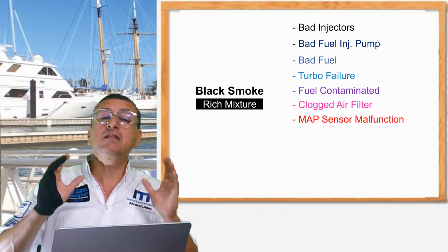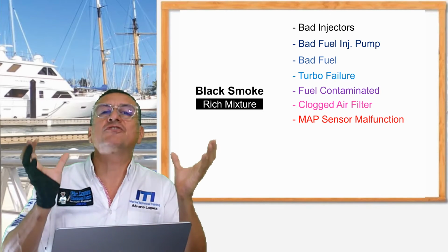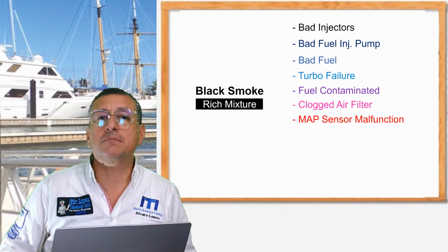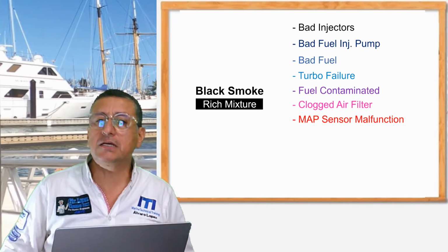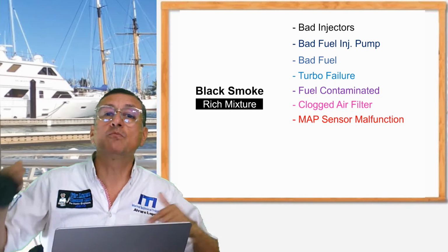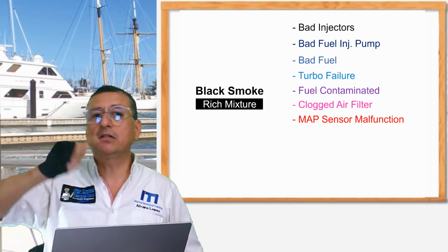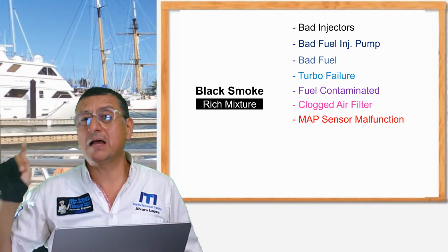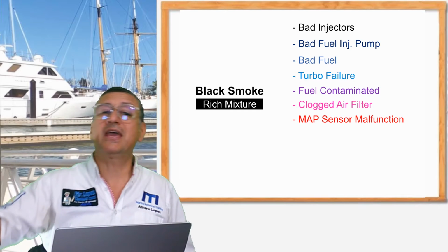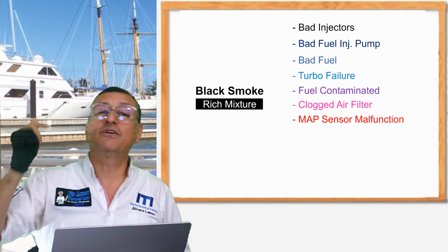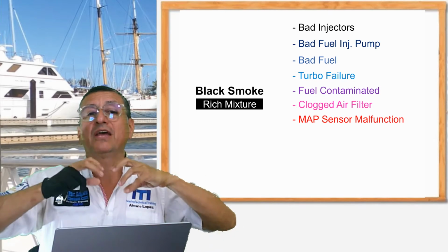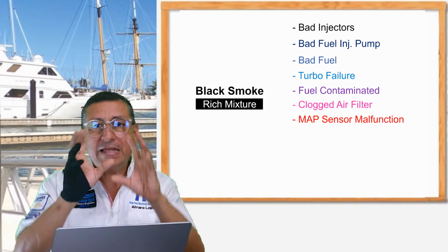If you remember, in the intake manifold you have vacuum, you have suction, and that sensor sends the pressure, the negative pressure, of that manifold. If that sensor is erratic, if the signal is not good, the engine compensates with more fuel. That sensor sends the signal to the computer, and the computer, with other parameters coming from the oxygen sensor, the throttle position sensor, and the temperature sensor, sends the information to the fuel injection pump, to the fuel system, to introduce more fuel or less fuel. That's nice, no? This is a complete diagram.